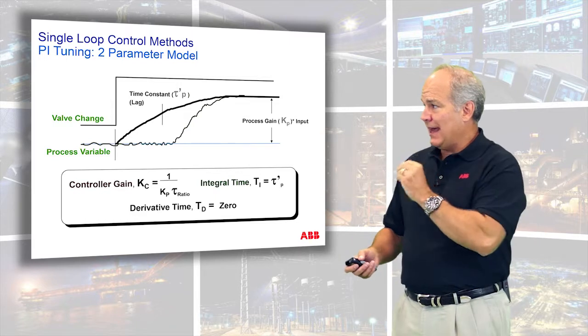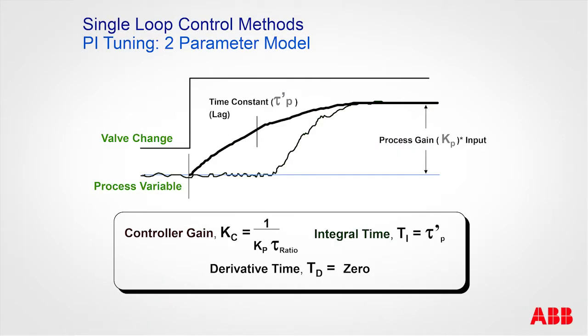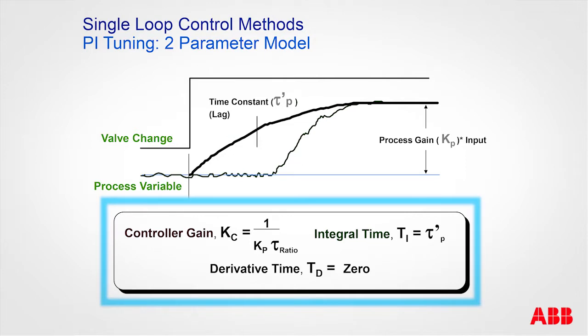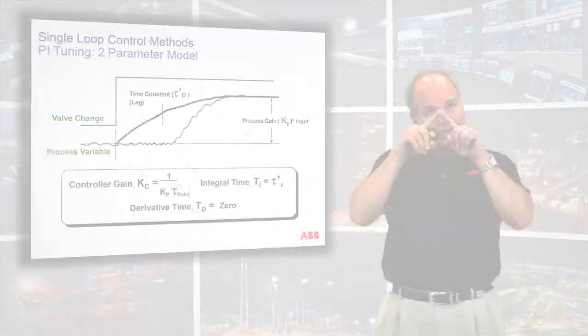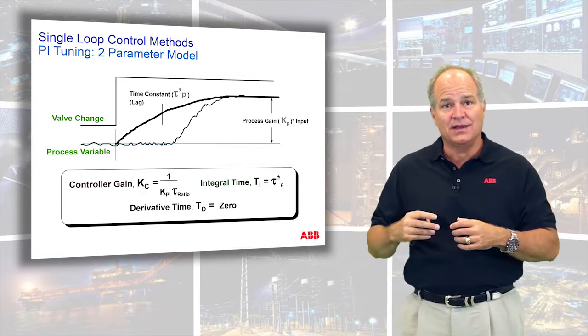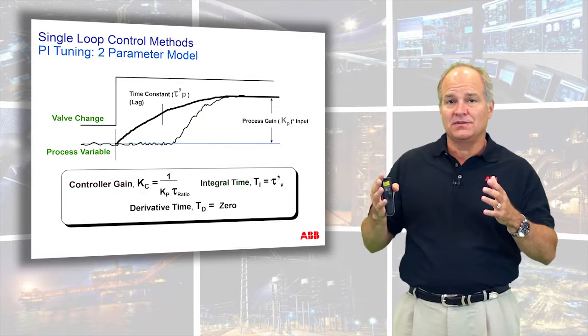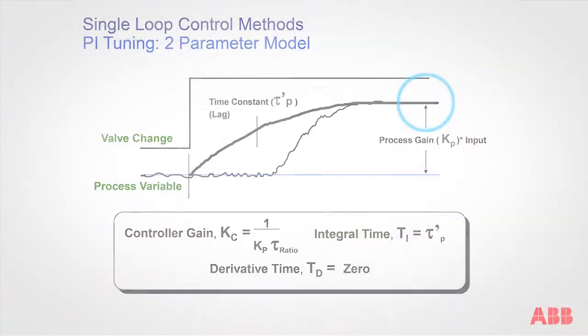In this case, that parameter no longer holds true, because you can see this section in the middle is what we call model mismatch. And I still recommend starting here, and this is a throwback from our discussion that we just had, where you calculate the time constant, and you can see the dead time is rolled into the time constant. So that's this little tick or this prime. It's sort of a calculated time constant. Sometimes you'll see a little hat or a prime. It's not the real time constant. It's made up. So 4 of those time constants is when it settles.